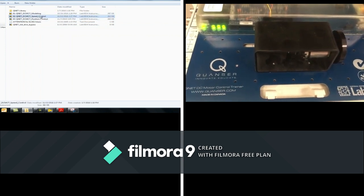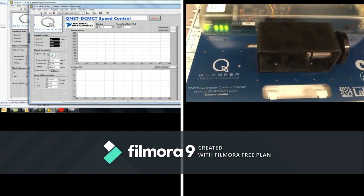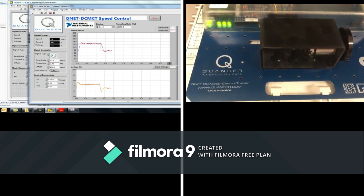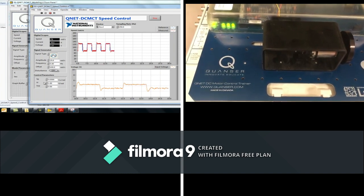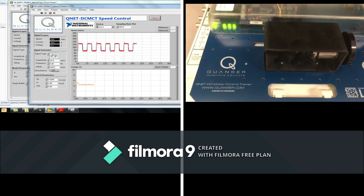For example, I can find speed control. If I open speed control, same thing, I select the proper device and run the experiment, we will see that we have a specific signal, the reference, the desired value of the DC motor. Let me just move this to 30. So we have our reference and then we have our measured. This is different than modeling. So now I'm controlling with the PI controller, proportional and integral gains, in order to give a specific voltage to have a match between reference and actual.